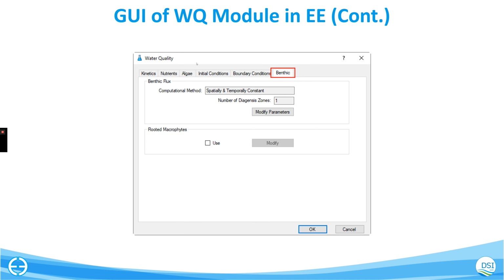It's just cranking along, totally ignoring what's going on in the sediment transport module. That is something that we need to address, but typically you're not simulating a water quality module with a really active sediment model. If you're simulating sediments, it's more just TSS, you get some deposition, you're not really too worried about it. But just so you know, they're decoupled from the sediment transport model.